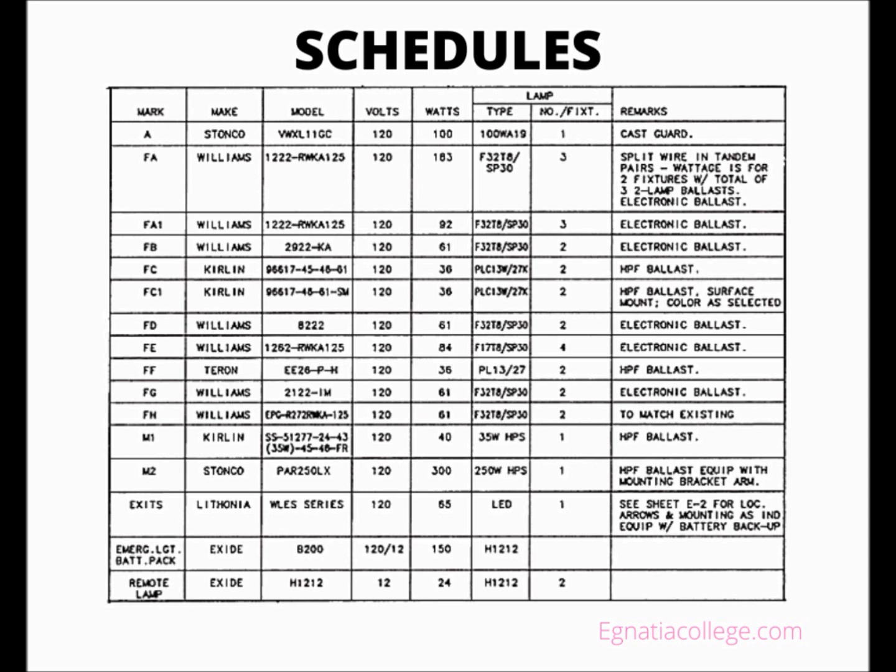A panel schedule identifies the panels by their mark or label. They are shown by this same designation on the electrical floor plan. The panel schedule for the School Edition lists each of the branch circuits served by a panel, the calculated load for that branch circuit, the voltage of that circuit, and the number of poles and trip rating for each circuit breaker. A panel schedule also might include type, surface or flush, panel main bus amperes, volts, and phases, main circuit breaker / main lugs only, breaker frame sizes, items fed and or remarks.